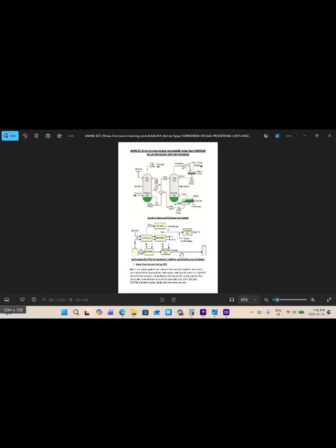The bottom process flow diagram shows the atmospheric distillation unit in the refinery and the sour gas header. All the sour gases are gathered from all the plants and headed to amine treating. This is on top of the atmospheric distillation unit, which goes to gas processing. All the gas from different units, from the hydrotreater and the isomerization plant, is headed to gas processing.